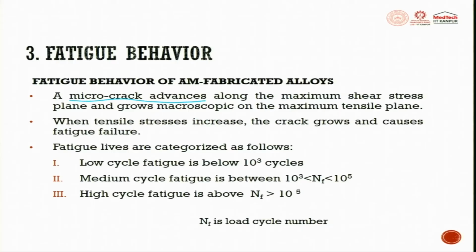Micro crack advances along a maximum shear stress plane and grows macroscopically on the maximum tensile plane. Very important point to note.